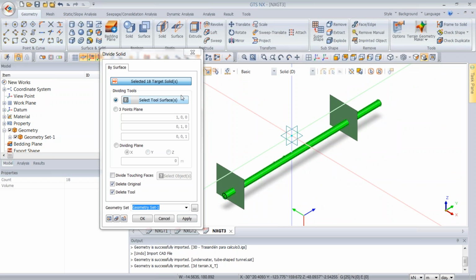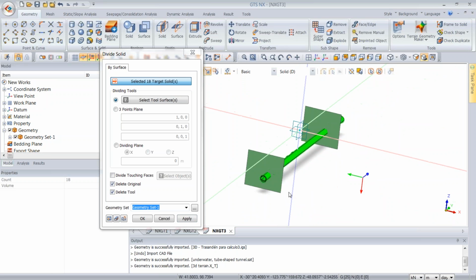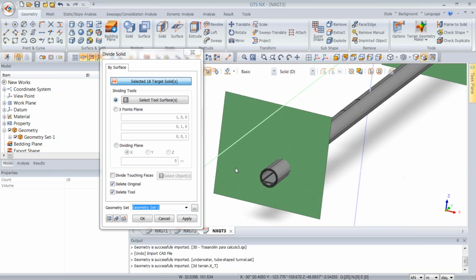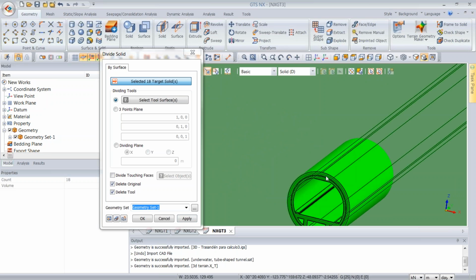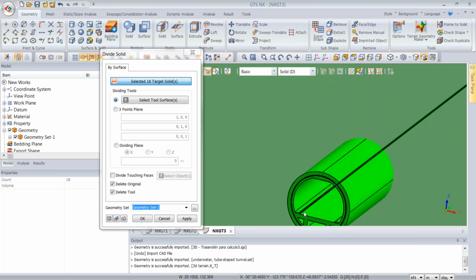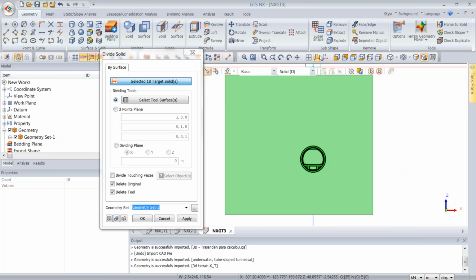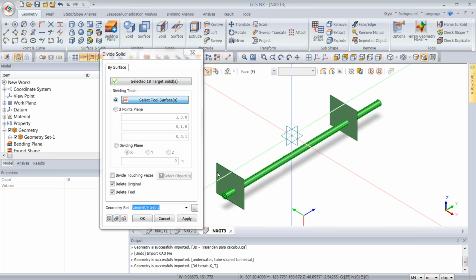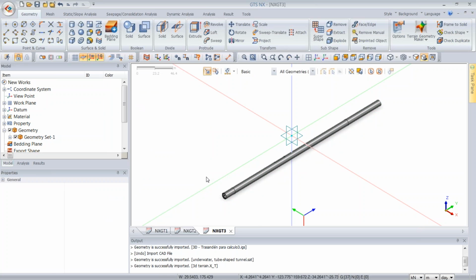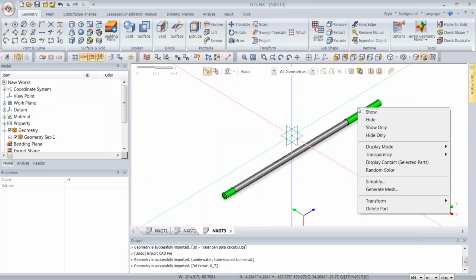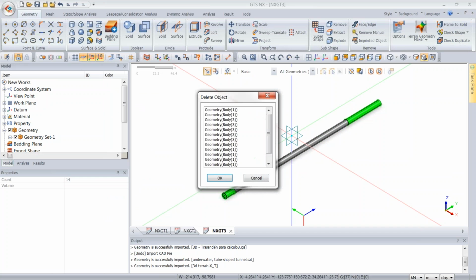I find it easier to, since this tunnel, this AutoCAD file that I have found, is actually composed of several rings and a few other geometries inside, it's easier just to select everything by going to the front face and drawing a small square. And then the tools are these 2 planes. And we see here now if I draw a square, there's 2 sections there, and I can also draw a square there, right-click, and delete these parts.